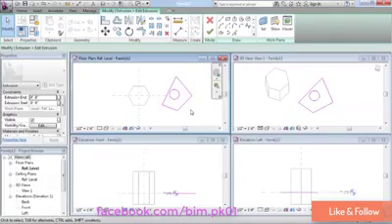It's by far our simplest form. Extrusions are the simplest of our 5 forms. We need only the single sketch, as we've seen, to create them and an appropriate work plane. But despite their simplicity, extrusions are widely used in most families and really are the staple of form creation.